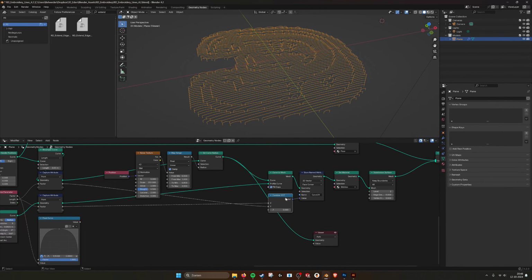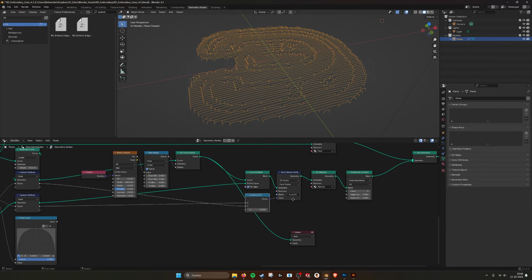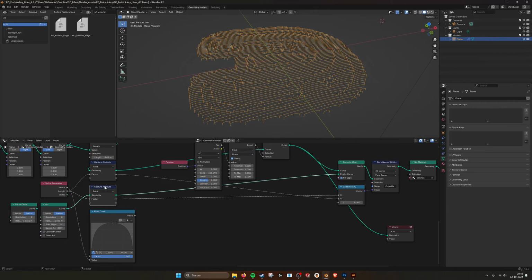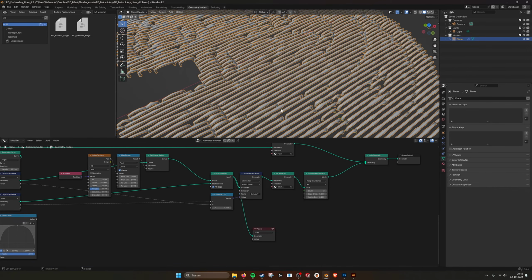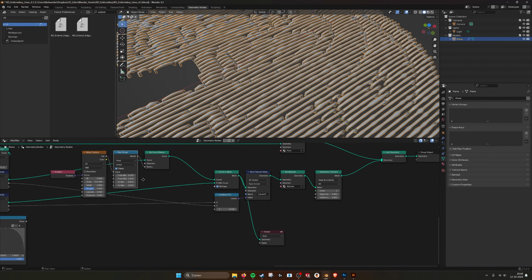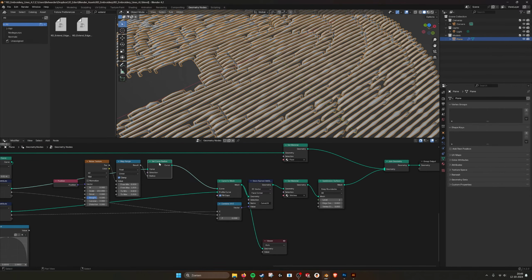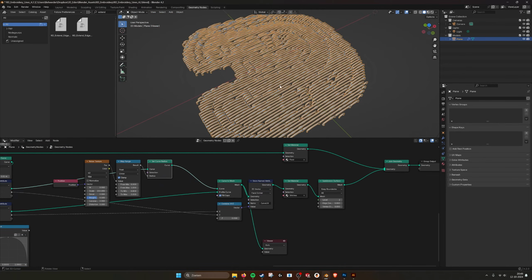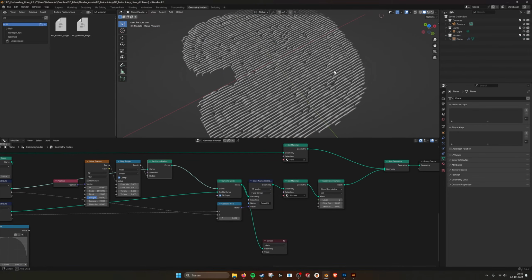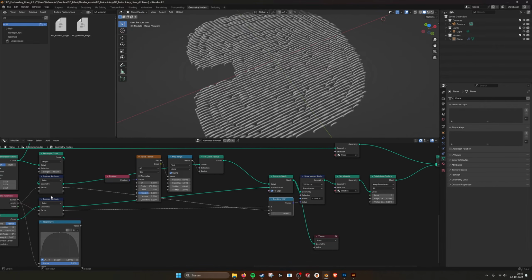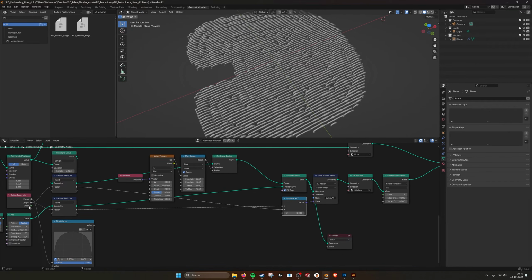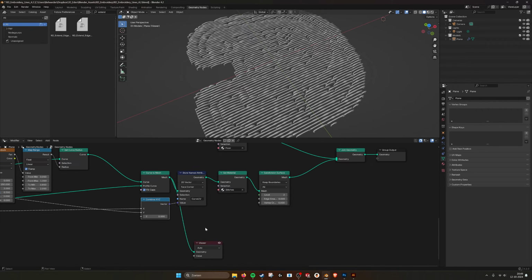it's an easier way to make the UVs, because you can unfold it by using this capture attribute and then use the spline parameter. So if we plug this one in, you can see that this is by the noise and the position and the map range. I make it from 0.8 to 2. Set the curve radius, so you see that it has a little bit of randomness to it. And here then I capture and combine these capture attributes lengths, and that creates the curve UVs.